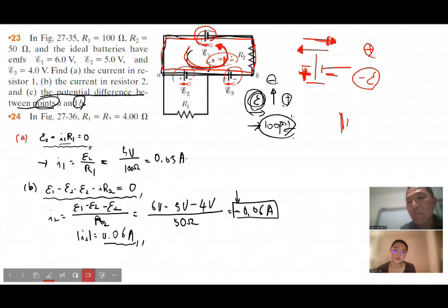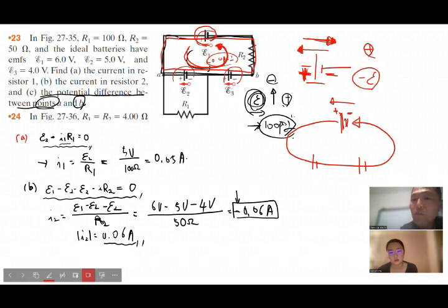One on the top, the other two on the bottom, and now you have a counterclockwise loop, and this one goes from minus to plus, right? Along the direction of the loop, it comes from the minus sign to the plus sign, the same direction. The polarity of this battery is the same direction as the loop you set up.